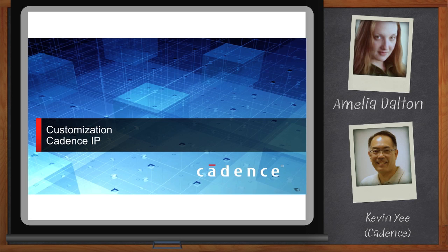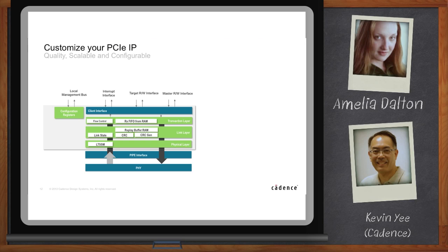To address that, we've architected our IPs to make sure that we give you a lot of customization in the IP. And one example of that is our PCIe. If you look at our PCIe IP, we have scalable bandwidth. So if you look at the PHYs, we can decide how many PHYs you have on it, how wide it is, how many lanes you're going to use. We can configure the interface, whether you have AXI on it or DMA, or how wide the bits, 32 bits, 64 bits, 256 bits.